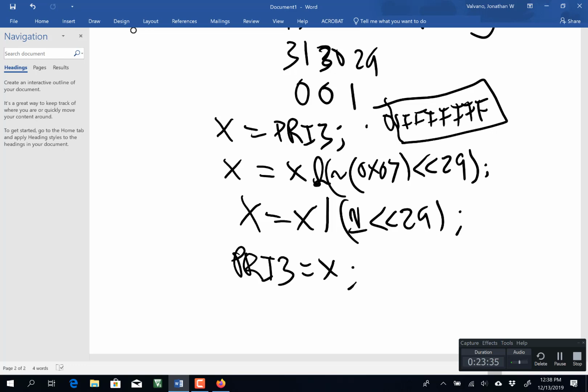Did I answer your question? The harder question is why in the world would I set it to priority 1? If I have multiple interrupts, this one is pretty important. Not the most important, but pretty important. A priority 0 interrupt could interrupt, but a priority 1 through 7 could not.